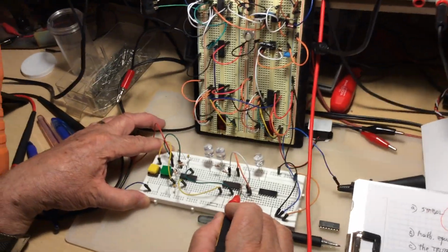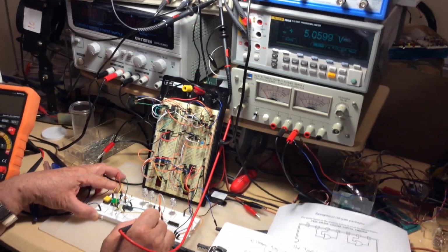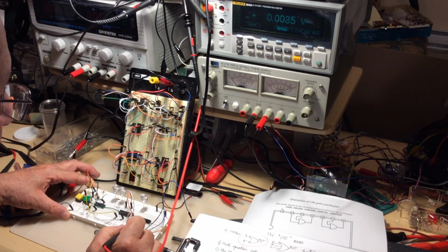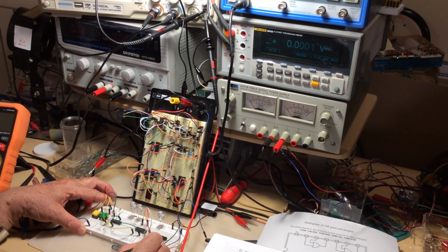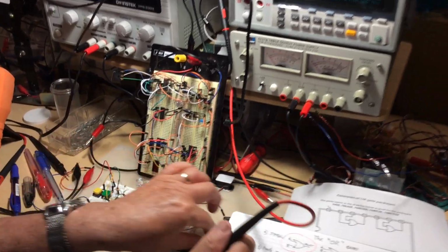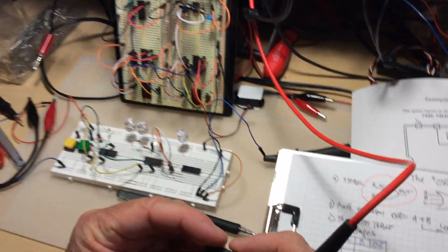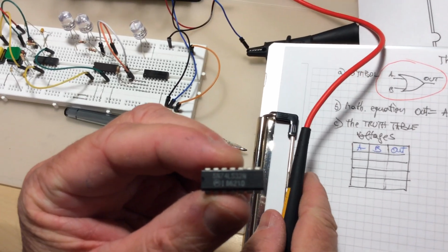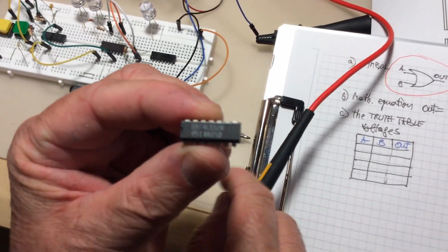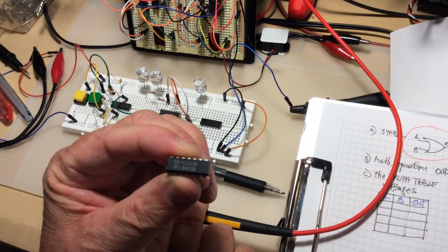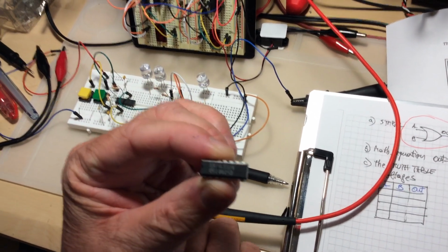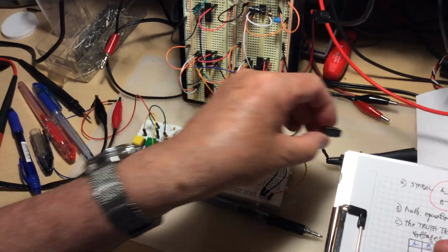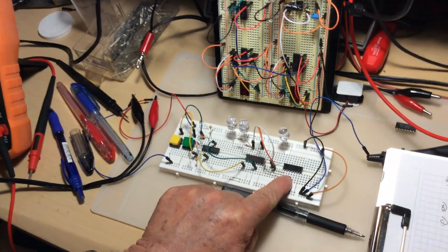And if I measure pin 7, this is going to be 0 volts. Okay, that's exactly the package. If you can see it, I have an identical one right there. And the OR gate we're going to use today has the code 74LS32. I'm going to come back to that later. Exactly that package, I have it over here.